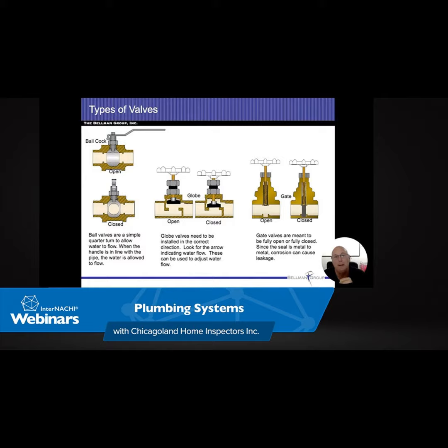So, flame rollout shields. Look for any sort of corrosion on the top. When you start seeing that rust and corrosion, typically we're backdrafting. Or I shouldn't say backdrafting, we got flame rolling out of the bottom there, or some sort of heat coming out of there, and that's what's causing the corrosion.